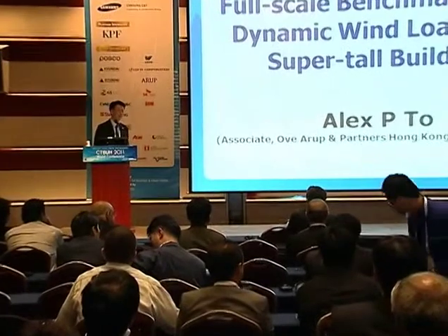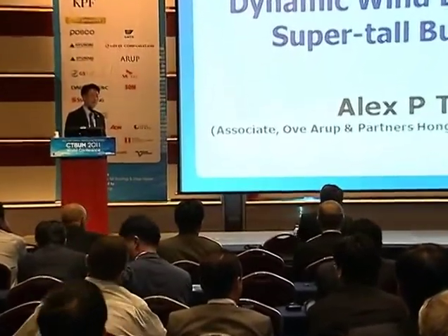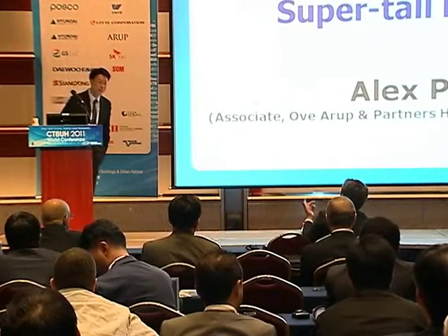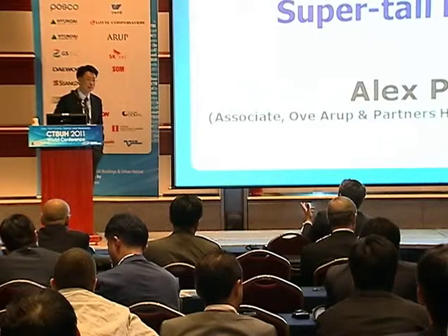Thank you very much. A very interesting presentation. I have two questions about damping. You showed the scatter of damping, including the negative damping, in the full-scale result. What is the reason for that? And another one is your newly proposed technique. It seems to be based on the frequency domain, right? In that case, the frequency resolution near the natural frequency is very important.